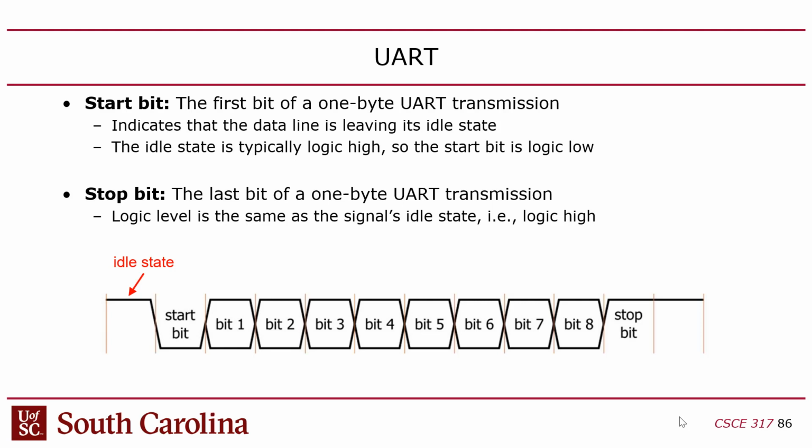Now the UART is designed for text, like terminals. So it's relatively low speed, and it's meant to be as simple as possible. You do have to understand there is a very simple protocol, though. Whenever you want to send a character or a word, you have to start out with a start bit.